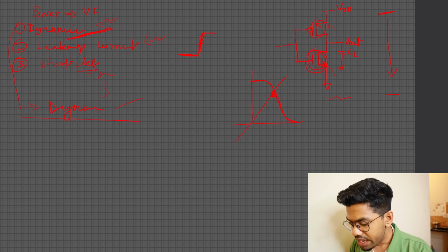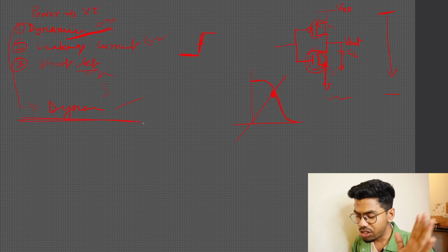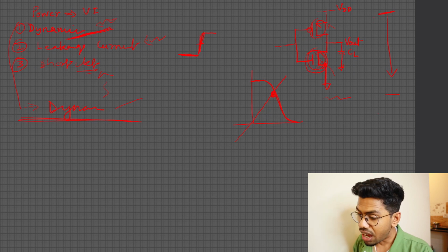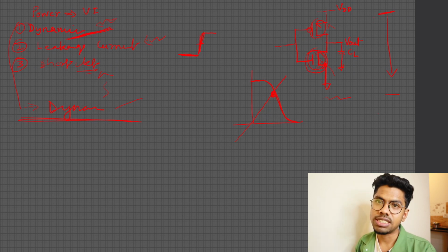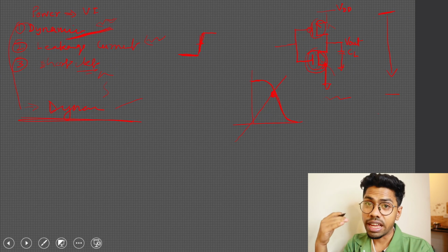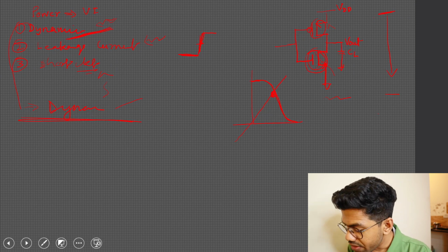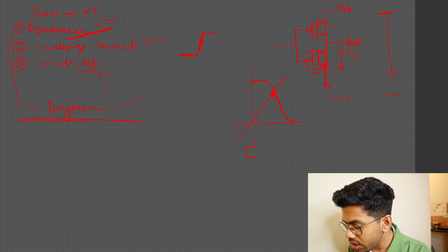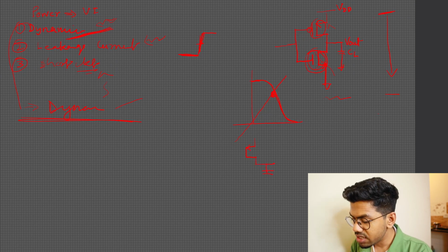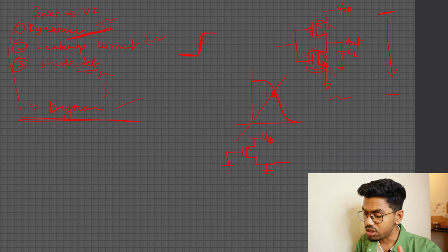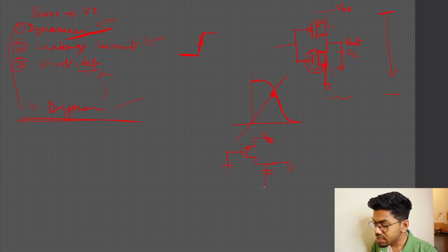But before I discuss dynamic power, you need to know how the power dissipation equation comes about. So see how the dynamic power arises. Consider that only the PMOS is on, that means at the input we have a low logic, zero logic, and our output was at zero. Output is at zero, which implies the capacitance we have at the output node.